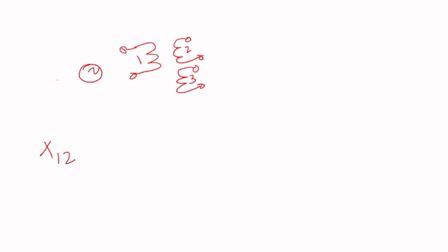Again, if I go back to, and I'm just going to show single phase again just for simplicity. So you have the 3 windings here. So if I want, for instance, x1, x2, so this is winding 1, winding 3, winding 2, 3. So you apply AC voltage until rated current of the winding you energize is circulated.